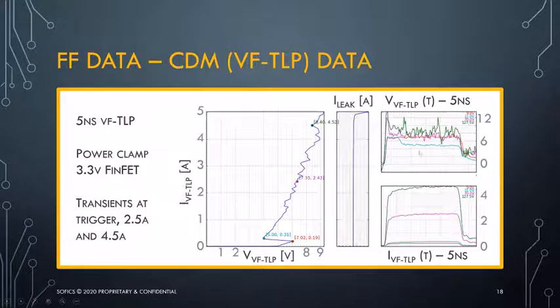What is interesting to see here is the voltage response. The voltage response that you are, by the way, seeing in this curve over here comes out of the averaging of the tail of the voltage transient. There is more information here in the initial transient or the triggering situation. You can actually see that from the red curve to the light blue curve, before and after triggering, there is less than a 1 nanosecond window where the clamp is triggered without any overshoot.